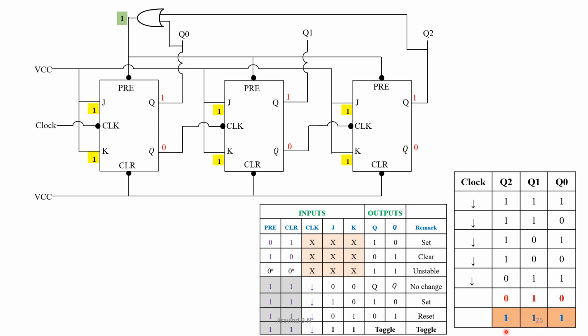We are going to get this value 1, 1, 1. So each of the flip-flops has got preset. Remember, it is not a reset, it is preset, and the output is now equal to 1, 1 and 1 for each flip-flop. So now we have got the initial value of the down counter, that is the highest value.